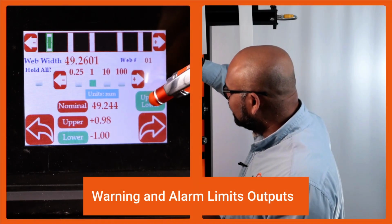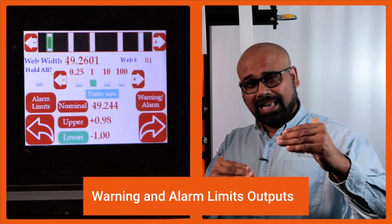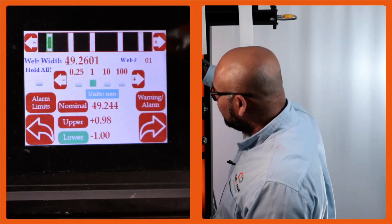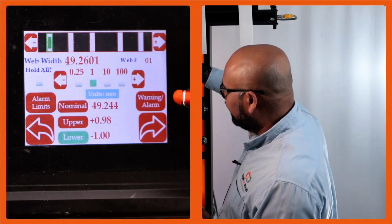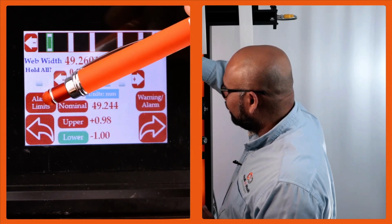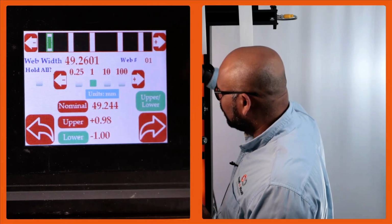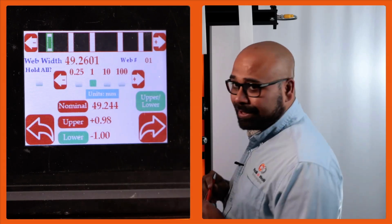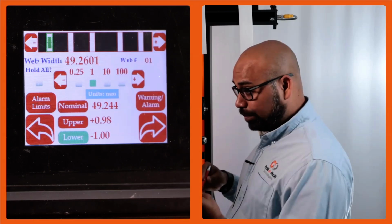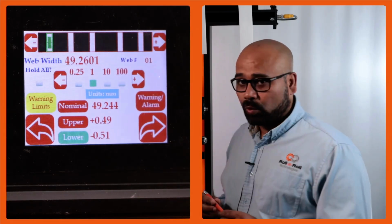If you want an additional layer where you want to set alarm limits and warning limits, then we can do that too. In this particular case, you need to make sure that it is in alarm and warning. When you have this in alarm and warning, you have this button show up. Just to show you one more time, if I have it just on upper and lower limit, these are the two parameters we can enter. But if we are in warning and alarm, there are 4 parameters we can enter. The first 2 parameters are here, and the second 2 parameters are warning limits.